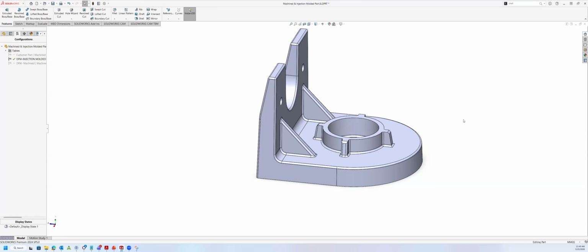And it also depends on the technology. Like somebody was saying earlier, if you're doing the honeycomb inside of it, you may not necessarily be looking at a production part if you're doing it out of FDM with the honeycomb. But you may still need to look at it and say, hey, I want to know how this thing feels, how it fits, how it works in the assembly. So sometimes those are great for prototype scenarios.